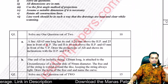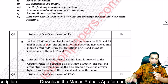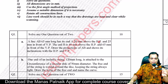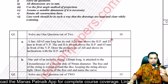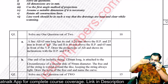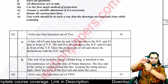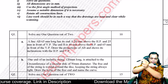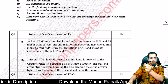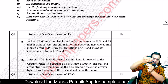A line AB 65 mm long. That's a line AB 65 mm long. Has its end A, this is end A, let's say, 20 mm above HP, 25 mm in front of VP. Assume my body to be the vertical plane, 25 mm from my body. End B, this end, is 40 mm above HP. So height from HP is 40. Very well. And 65 mm in front of VP. My body is VP, 65 mm from my body.